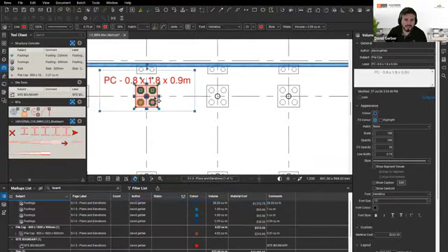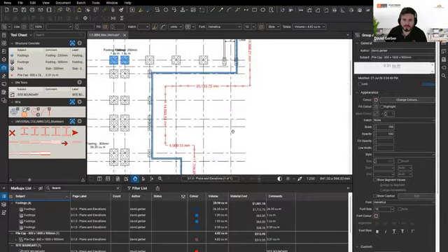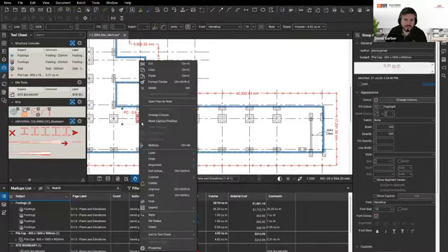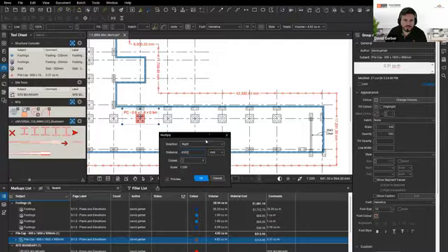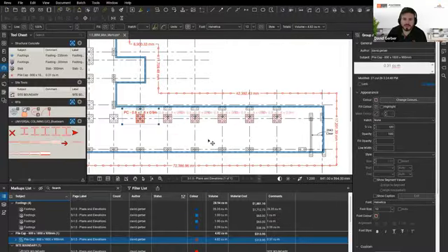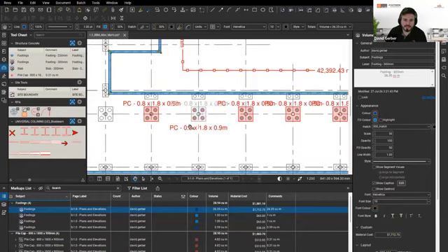And then instead of copy pasting, you could just use multiply instead. So just double checking 6502. I could just right click, go to multiply, and then I'm just going to change it to mils 6502. And I can pick and choose how many copies. And I'm saying to the right, but you can go down, left, up. So you can see very quickly I've copied them across and they're accurate as well because I've scaled the drawing.